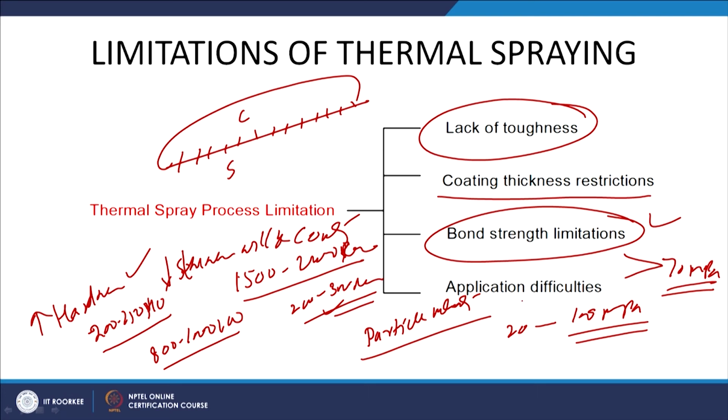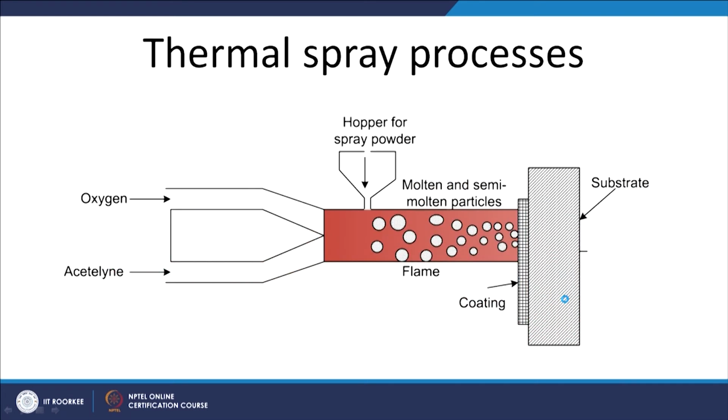And there are application difficulties, like the process has to be applied in the shop, and those difficult to access locations cannot be subjected to coatings using the flame spray process. So, there are a few application related difficulties as far as thermal spraying is concerned.